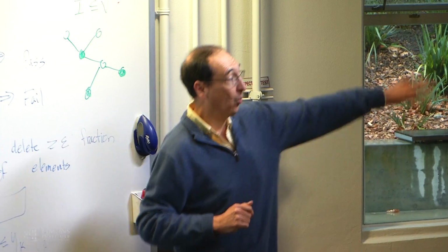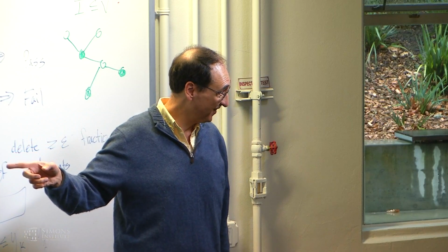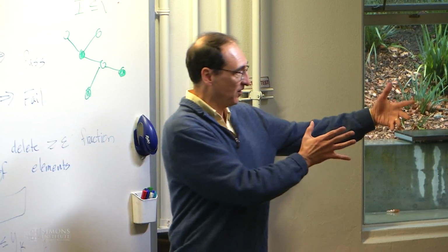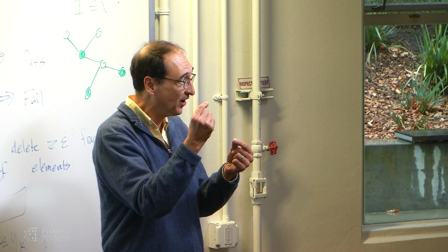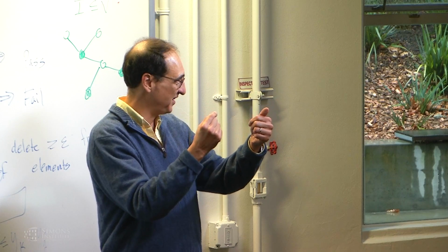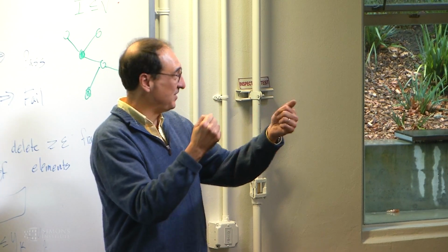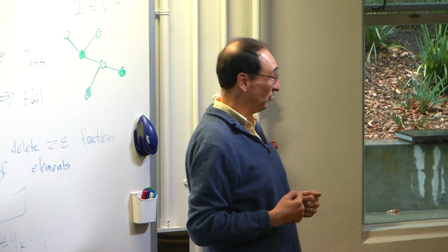So why not put them way out to the left? Well, you can do that, but you'll get very large gains, right? Because when you want to move those eigenvalues very far away, the K matrix is going to be very large. What does that mean? It means if I have a very small error between the actual state and the desired state, I'm going to apply a huge input. That might be okay, but if I had noise, for example, in my state estimate, that gets amplified too.